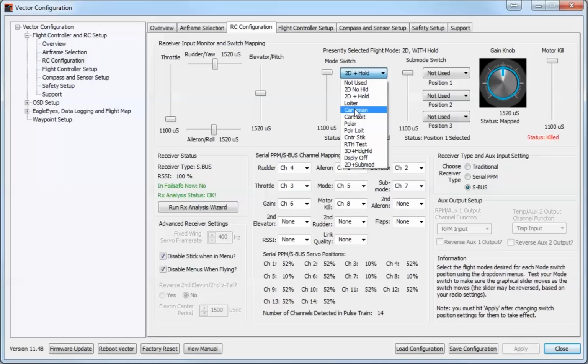So it's not saying, oh, come home. It's not the same as something like DJI's home lock mode, where if you pull down, it will say, well, I don't care what rate I'm in, I don't care what attitude the aircraft's in, I will always come back at the angle towards the home point. All this will do is fly back in the direction that Cartesian allows. It's a little bit complicated to imagine, but the key is to remember that it's not going to come back home to you even if you want it to.